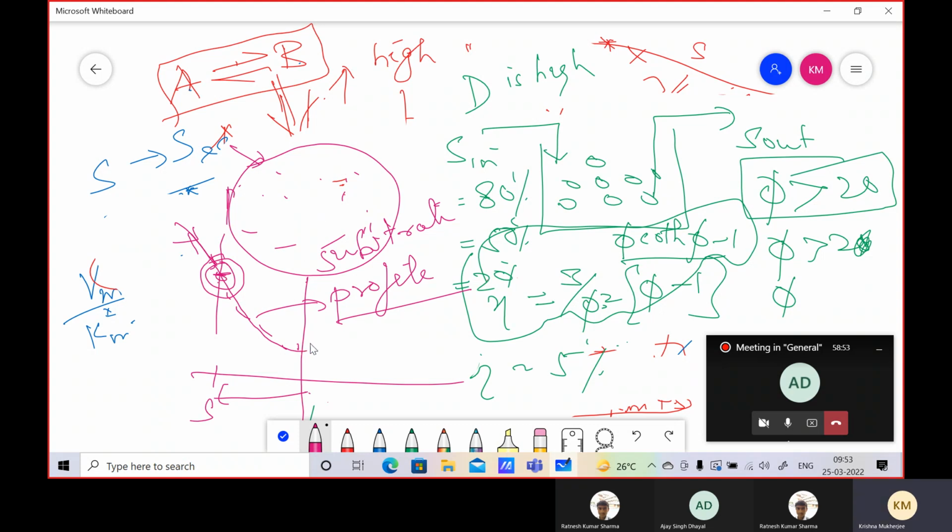We did a clever thing. We did not integrate this profile. We simply found the derivative of this profile and multiplied it by the mass transfer coefficient, because we know that the rate of substrate coming in is equal to the rate of reaction inside the bead, because the bead is not building up. In that sense, it is in some notional steady state. There can be no accumulation inside the bead, right? So what is the profile?